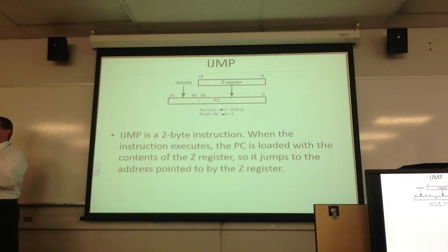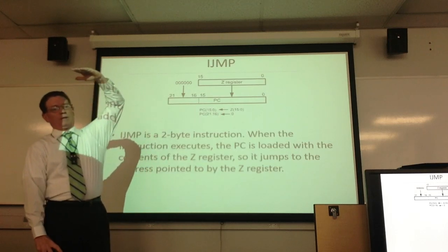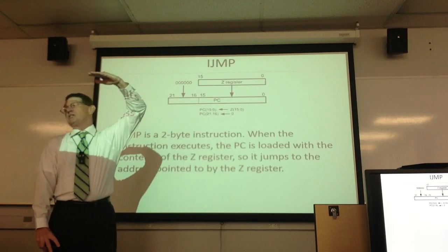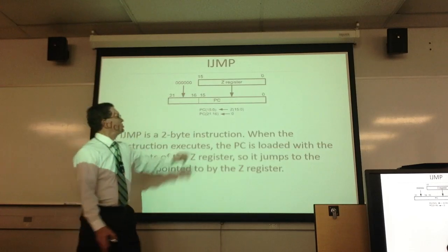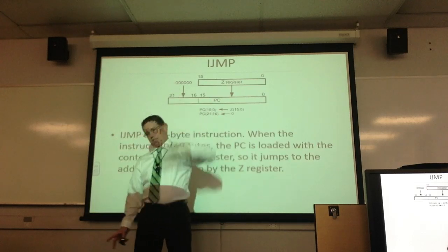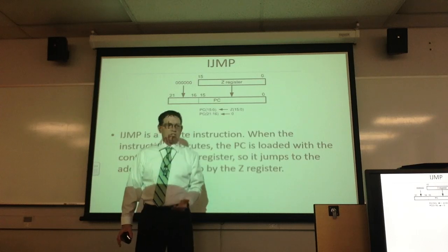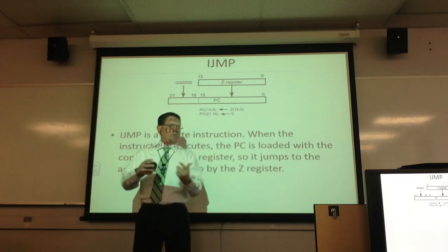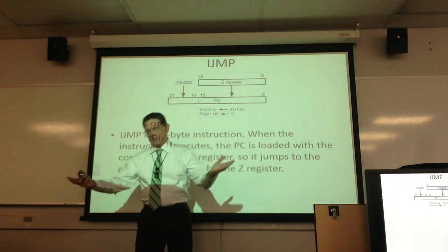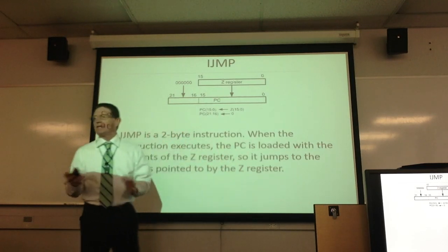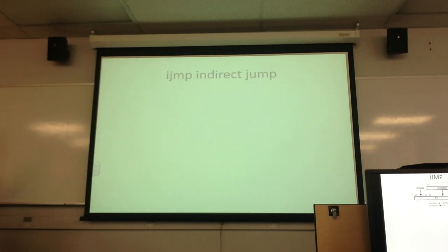Now the question is, I'm doing 16-bit addressing here. If I have a lot of flash memory where maybe I'm using 22 bits of addressing, just in case you have a really huge amount of flash, the Z register may not be able to access all that flash space. Then you use what's called the extended Z register, the RAMPZ. Remember, there was a RAMPX, a RAMPY, and a RAMPZ. Those you can extend out to 22 bits. But we're not going to worry about it. Everything we're going to deal with is 16-bit. Just to let you know.